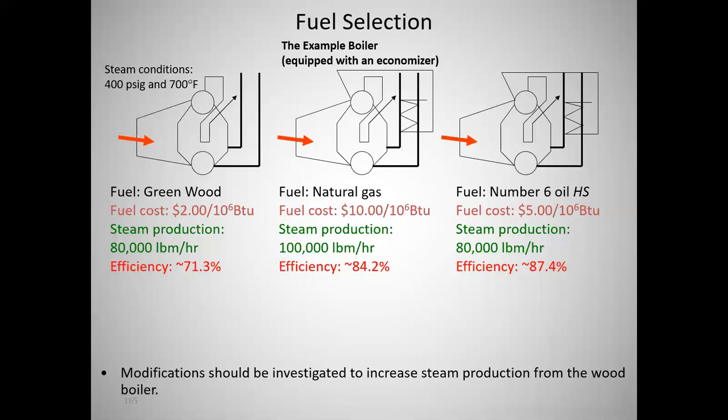It's probably the natural gas boiler because it's going to turn up and down better, quicker, react more quickly. That green wood boiler is not going to turn up and down very quick at all because it's got this big mass of wood in there that's burning. Well, you quit putting much wood in, you still got this big mass that's in there. Natural gas, you're blowing it in.